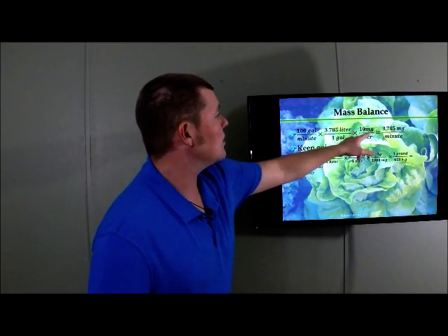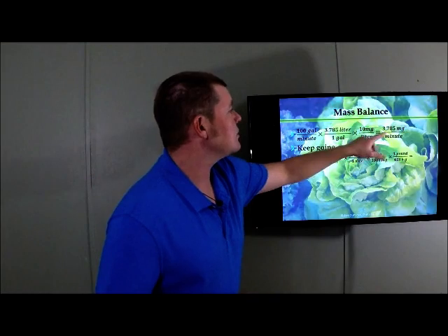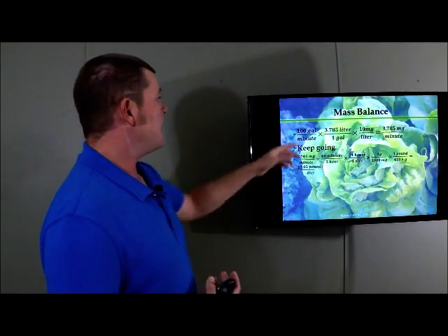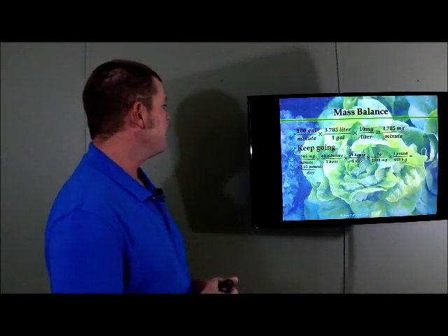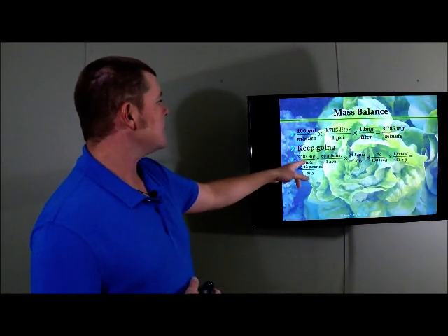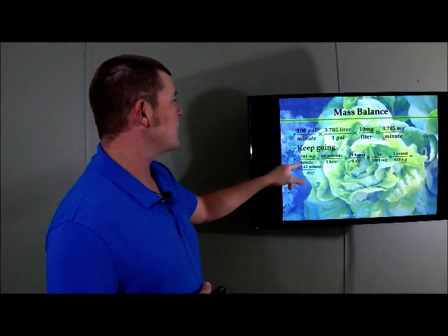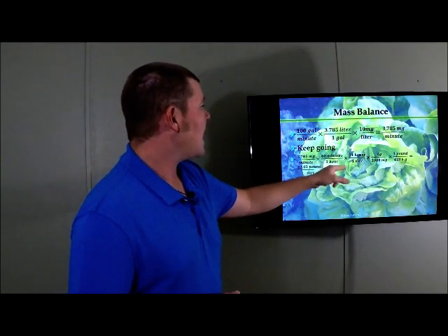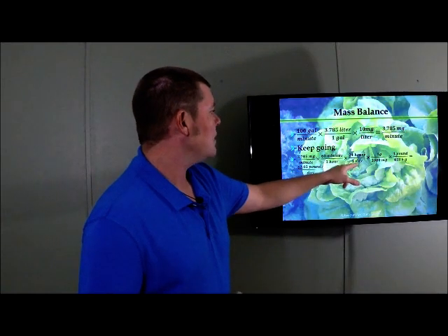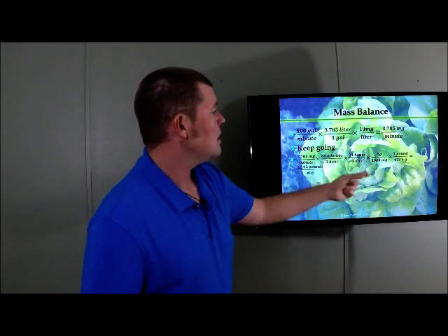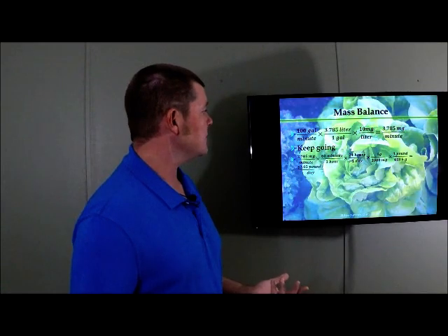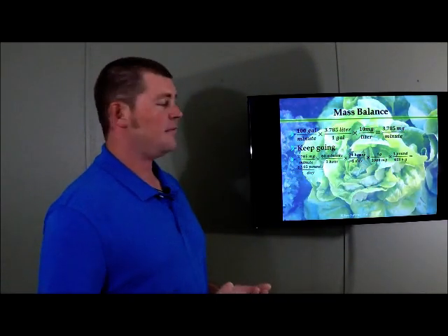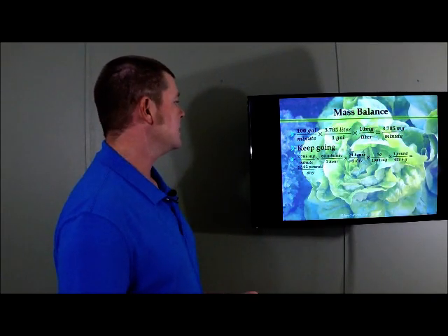As you can see here, we still have milligrams beside each other. These are not able to cancel out, so we have to go another step further and bring milligrams over to this side. So once we do that, we've got 3,785 milligrams per minute times 60 minutes in 1 hour times 24 hours in 1 day times 1 gram in 1,000 milligrams times 1 pound, which is 453.6 grams.